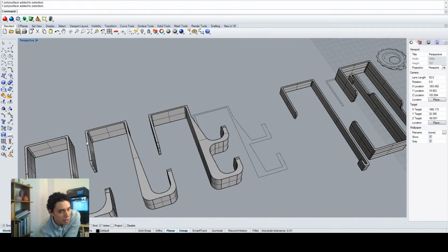It's also better, I would say, to have this section right here. It's going to add walls, and I'll talk about walls in a second, but it's going to add walls to my material, or complexity on the walls. That will also help with the beefiness of the part, specifically when talking about 3D printed objects, right? If this was injection molded, removing material would probably weaken it. Since this is going to be a 3D printed part, adding a little bit more surface area to those walls,